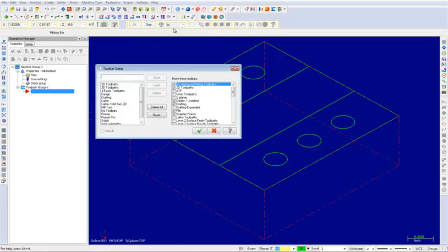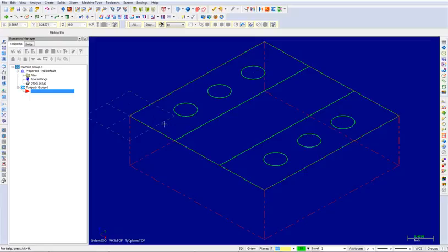From here, select the 2D toolpaths, and you should see the 2D toolpaths icon appear on the left side of the screen. Choose Load, and press the OK button. The toolpaths will appear on the left side of your screen.